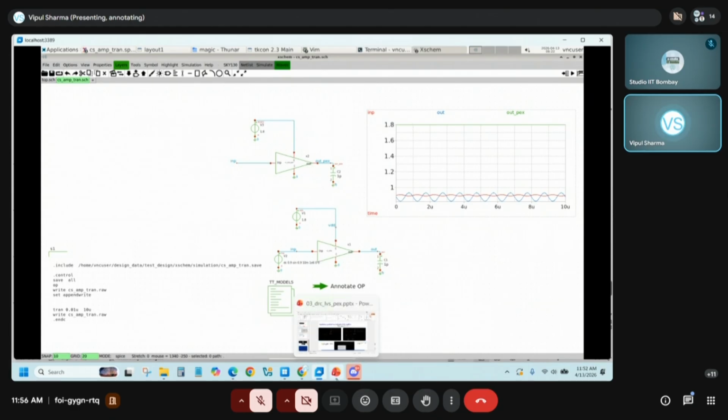So yeah, I think this is all about the steps which need to be followed. Once this is done, post-layout simulation is done, and you are happy with the results, let us say all the waveforms are matching, and if we are interested in AC analysis or transient specs like slew rate, rise time, fall time, and all those specs are meeting even after the parasitic extracts are taken into consideration for simulation, then I think the design is okay, and we can go ahead with sending it for fabrication. So these steps are required.